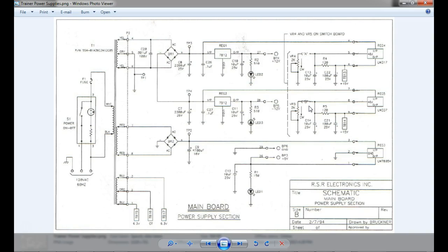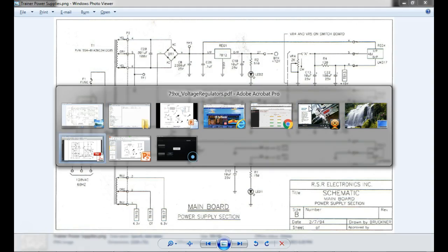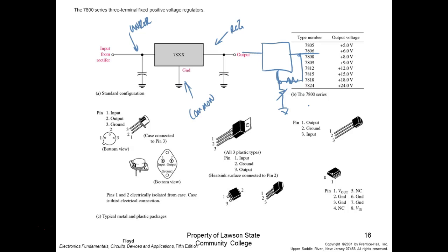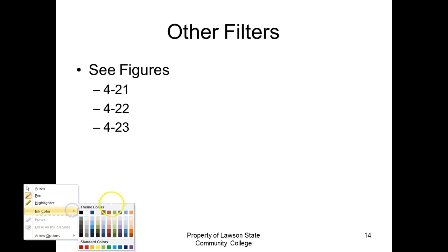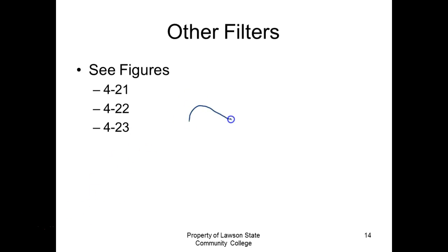So what we have to do is make sure that we give that thing enough voltage so that dip or that valley does not get into my regulation. You understand what I'm talking about? So that means if I come over here and I've got this unfiltered DC that's changing with current, it's changing with load, then my regulator is going to have to regulate down in here. Because if this ever dips into my regulator, then we've got problems, right? So when you figure your ripple voltage for that current, make sure it never drops into where you're trying to regulate.